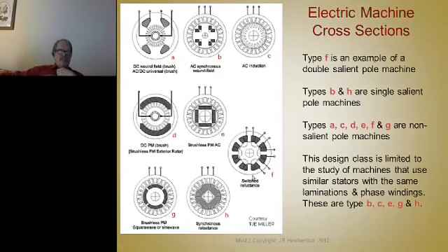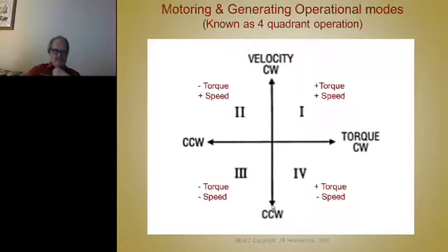So in reluctance machines, the torque and performance you get is based upon how well you can create this saliency, or how big of a difference you can design into the geometry such that one inductance is a lot higher than the other one. So the inductance ratio is equivalent to the saliency ratio in these kinds of machines. That's what I wanted to point out. But we're not studying the switched reluctance machine in this series because it uses a different stator, different winding. It's a whole different design topology, so it's not easy to compare it with these other machines. We'll have to treat that as a separate topic all by itself.